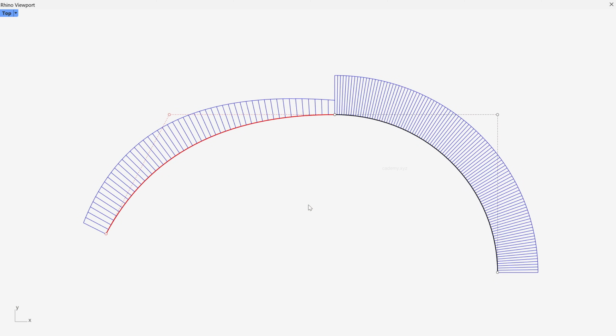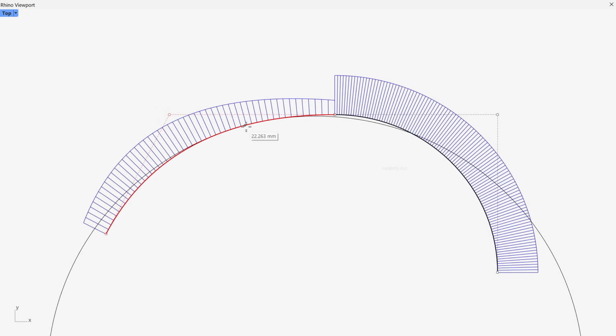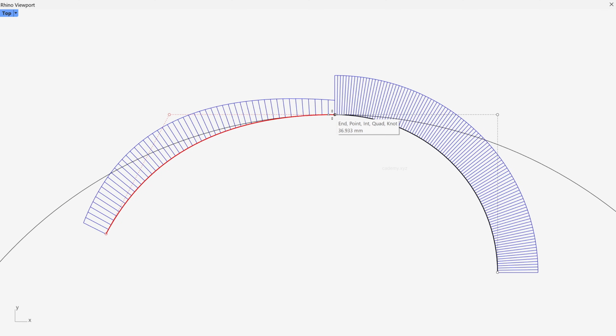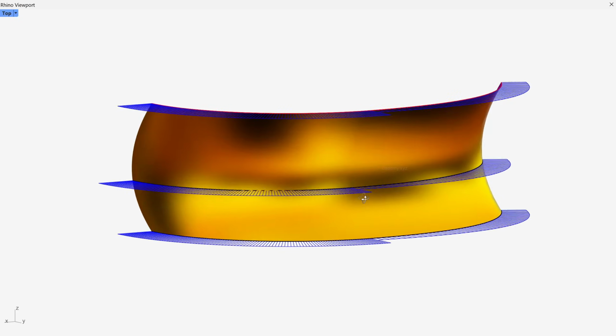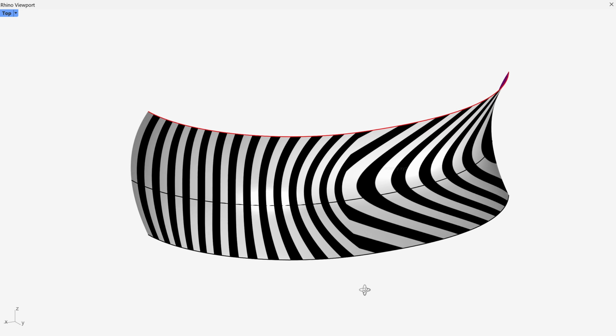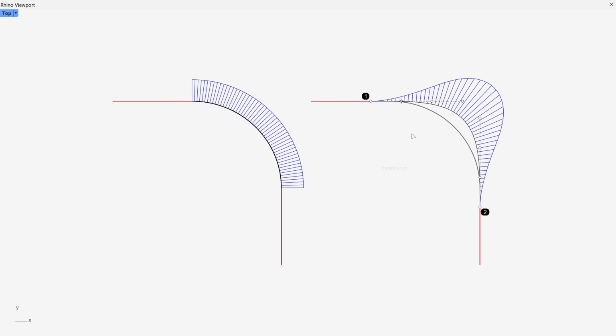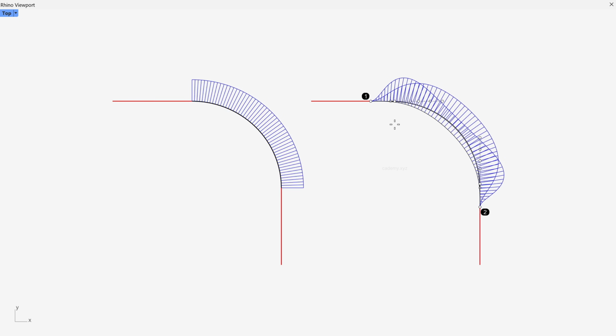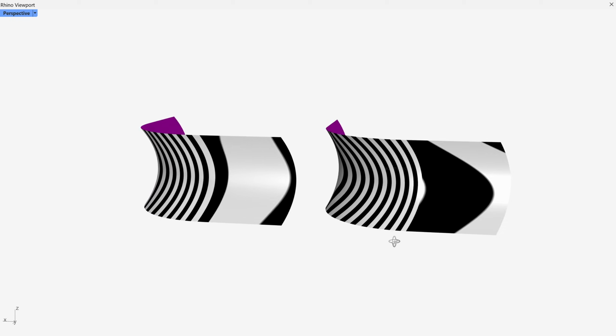Now let's talk about fillets. G1 fillets are tangentially continuous, but they often create undesirable highlights. And the reason is simple. The radius of curvature of surface A is not the same as the radius of curvature of surface B at the junction point. This sudden change in curvature is what causes visible reflections to break. Instead of accepting that, we will see how to mimic a simple fillet using a BlendCrv, allowing us to control how curvature ramps up and dissolves across the transition.